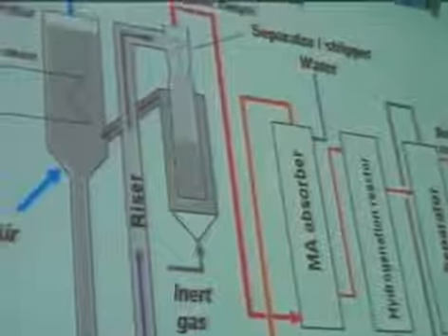And now, the first example. This is the DuPont process, a very original process to oxidize normal butene to maleic anhydride in a system with two separate fluidized beds. In one fluidized bed we have the stage of oxidizing the catalyst after reaction, and the second stage is a riser system where the normal butene will be oxidized to maleic anhydride. And it is very important to have a stage of purge by inert material to remove the products of the partial oxidation, in this case maleic anhydride, from the surface. Okay.